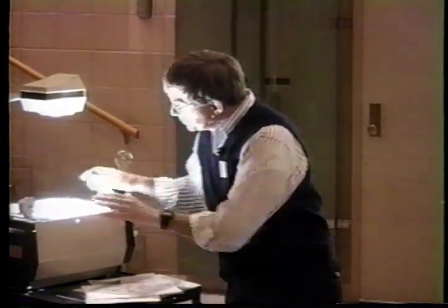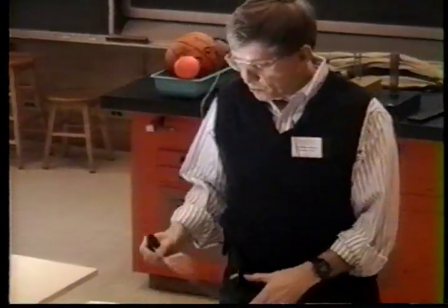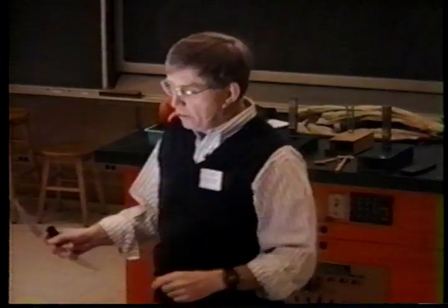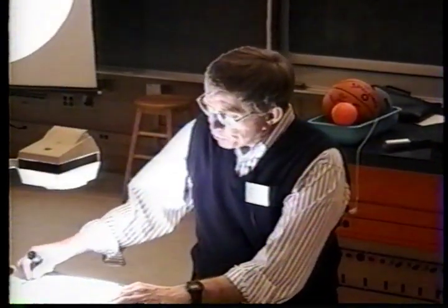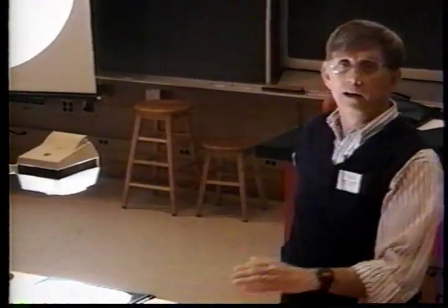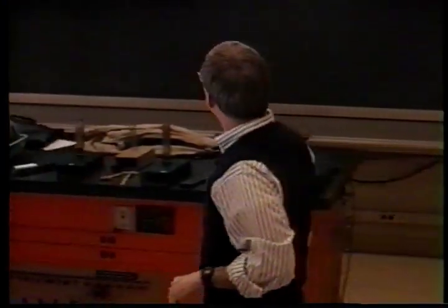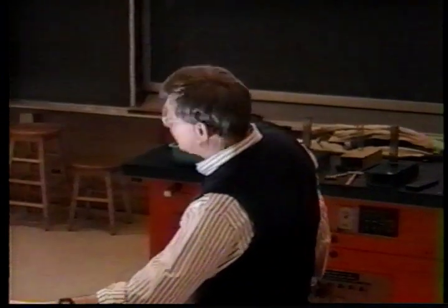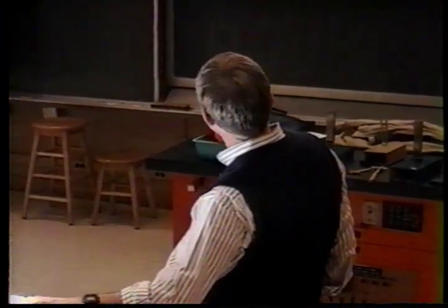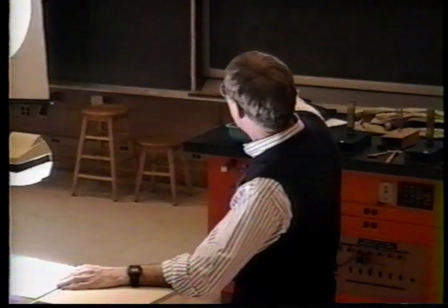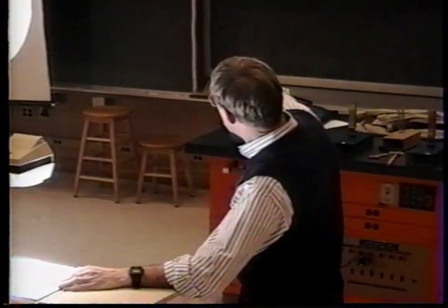These kinds of differential things were never really dreamed of when the initial system was defined. And so their use, which has become standard in survey, is defeating the selective availability. And there's a big issue going on about turning that off because of the importance of the greater accuracy, a factor of 3, sometimes a factor of 5, that commercial users would get, and civilian aviation would like that factor of 3 as well.